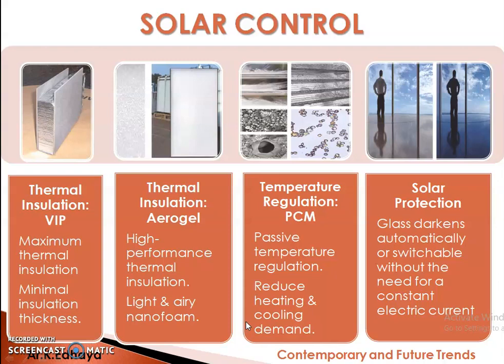So these are vacuum insulation panels. These panels come in standard sizes, and you cannot drill it, you cannot cut it. If you do anything, then the insulation effect will get reduced. If you want, you can customize those insulation panels and get them used in your building envelope. So this can be laid on your floor, on your walls, and on your roofs as well.